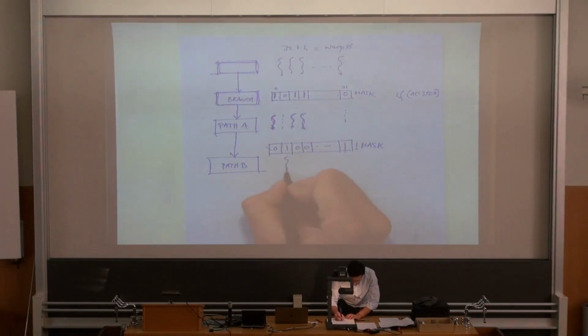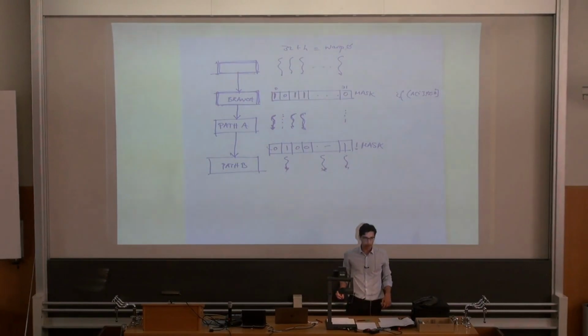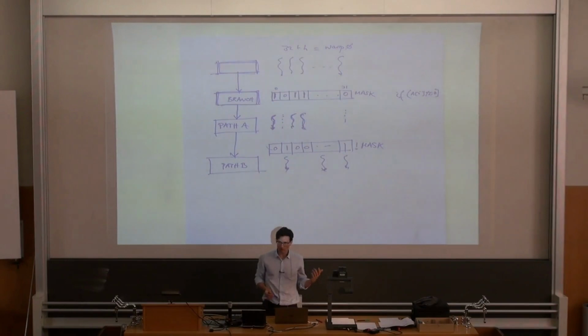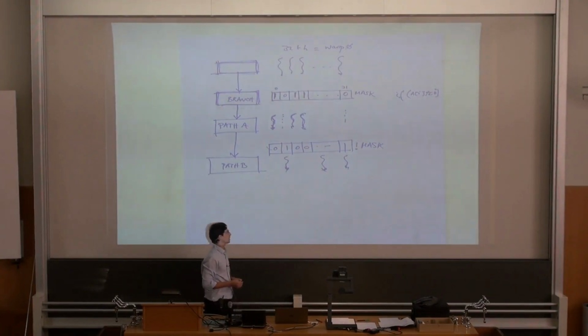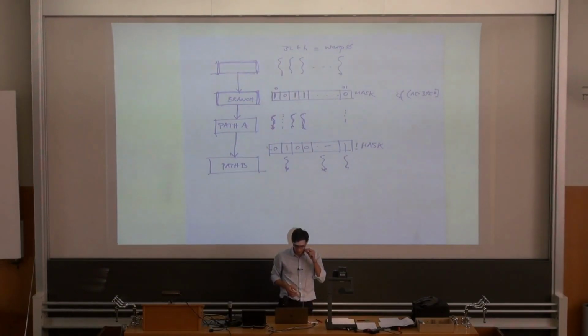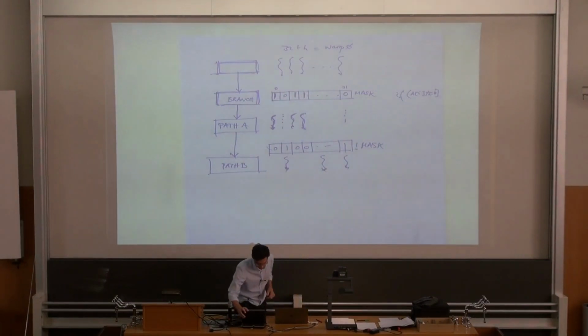So we will have now this thread working, and maybe someone else somewhere there. So this is how GPUs implement predicated execution. As you can see, it's a similar way to the conditional execution that we have seen before for the vector processors. And about predication, as I said, you will have more details next week.